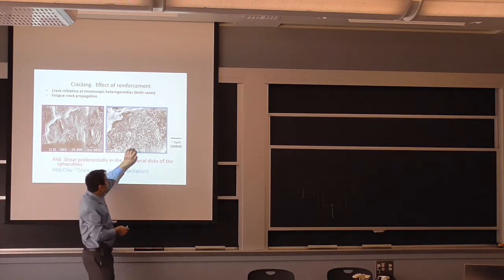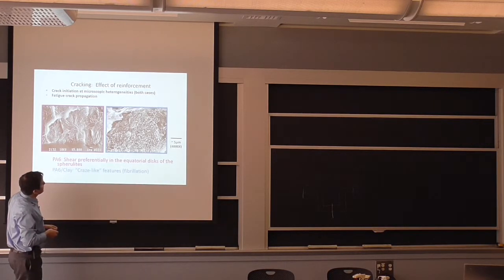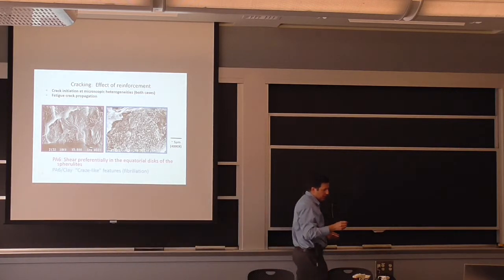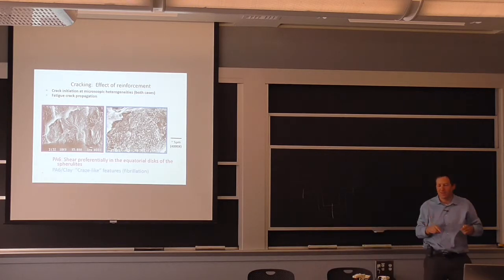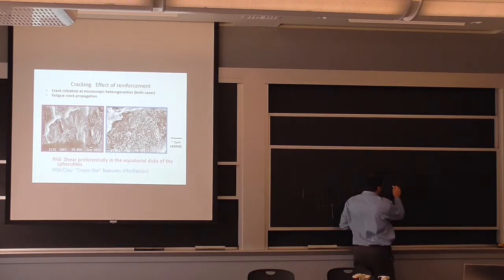I'm showing next to it an example of a nanocomposite. What happened here is you introduce nanoclays. The reason we call them nano is their thickness, but they're very small layers. They're very cheap because you can exfoliate these layers from natural clay by chemical treatment. Clay is a very layered structure, so you end up with something of the order of a nanometer in thickness, but all these other dimensions are in micrometers. So say we have 0.1 micrometer here, for example.